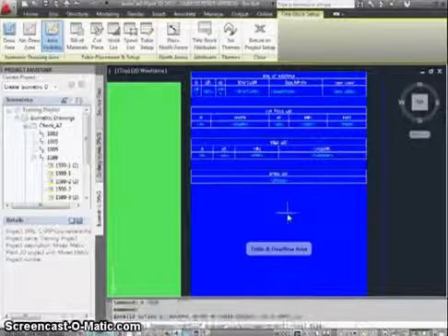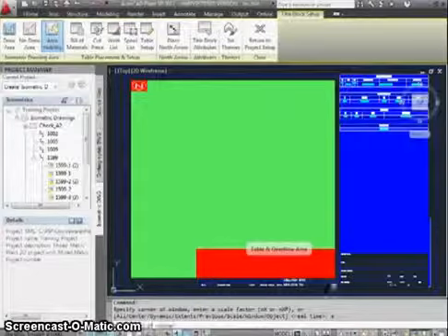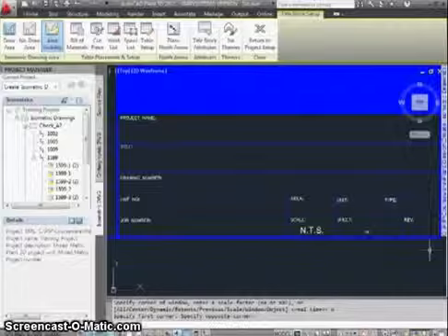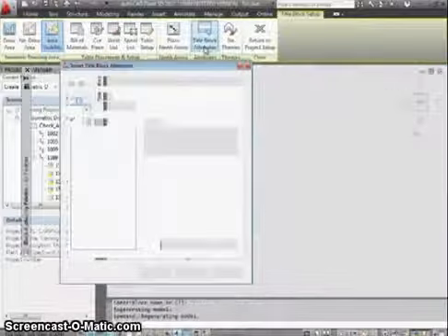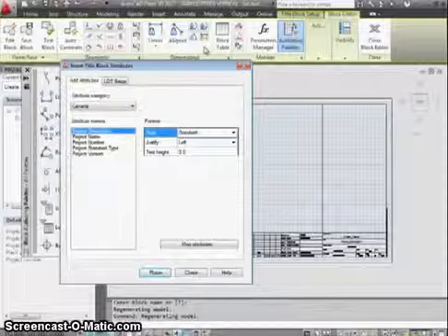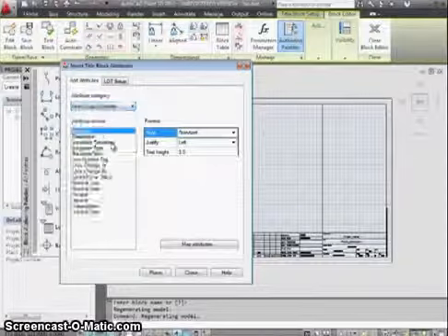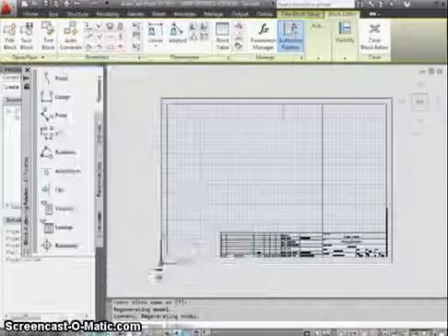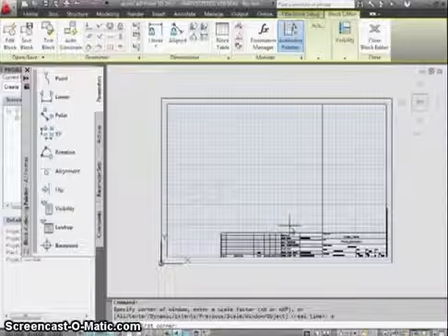Okay, now we're done with the table areas, let's take a look at the title block area itself. Attributes in the title block are regular AutoCAD attributes, but their values can be provided automatically with the ISO as it's created. Let's add a new attribute to the title block. In the ribbon, click the title block attributes, select service property, and select place. We'll use a transparent zoom and locate the attributes in the title block.